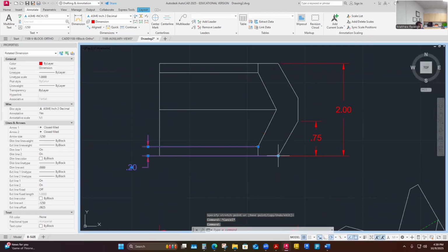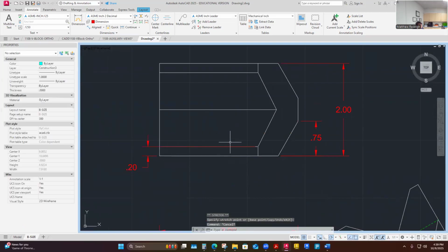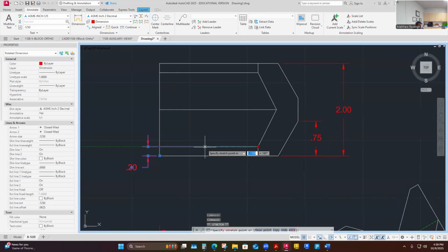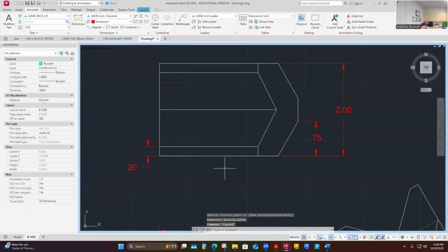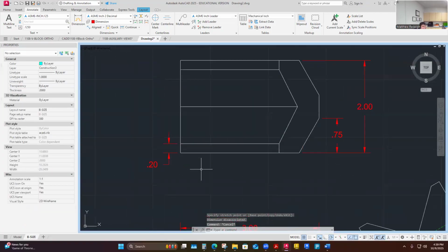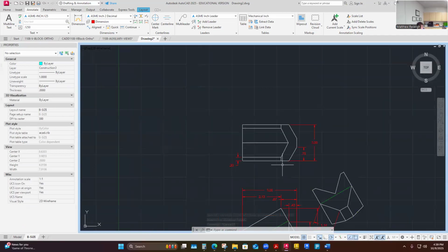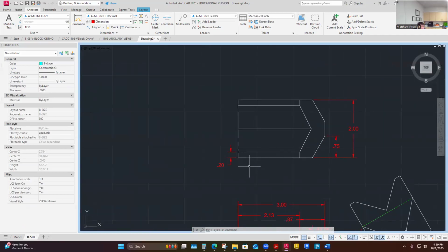It's because I'm looking ahead at what the next dimension is, and I'll show you why here. So really, I'm going to get rid of all of this overdrawn extension line work. And obviously, it's closest to here, and it still is pulling from the front. I know I'm breaking the rule of it not being in between views, but it's definitely not breaking away from where I'm controlling the dimension from the front surface.